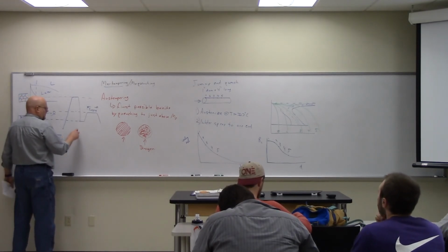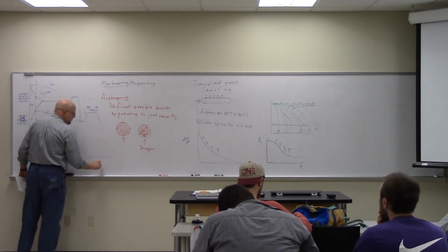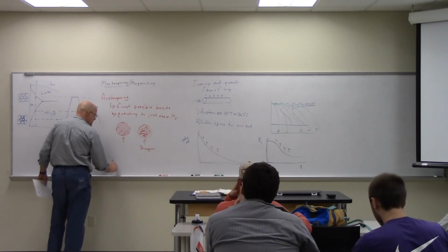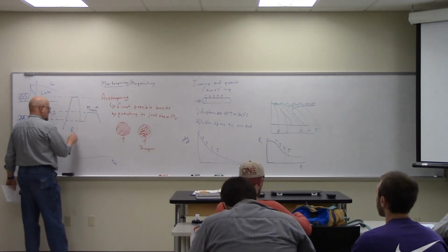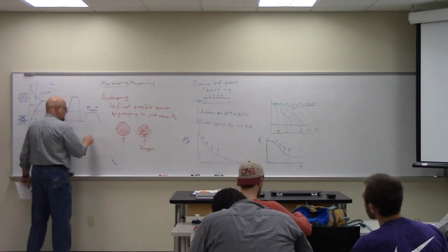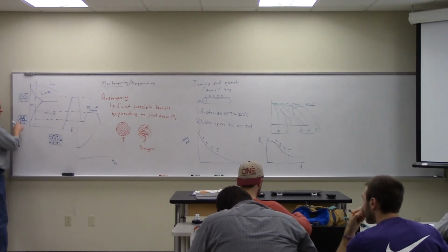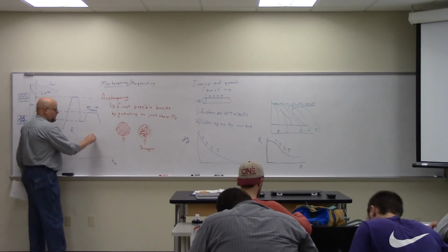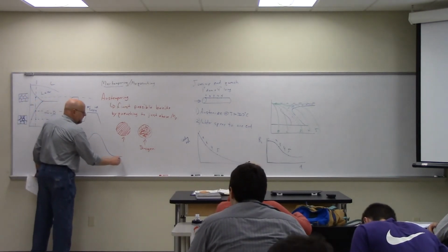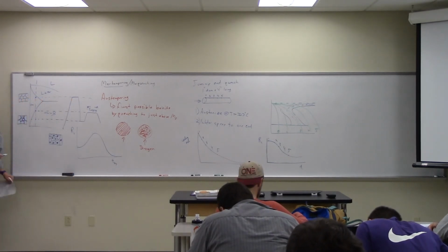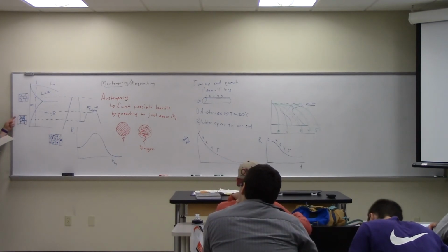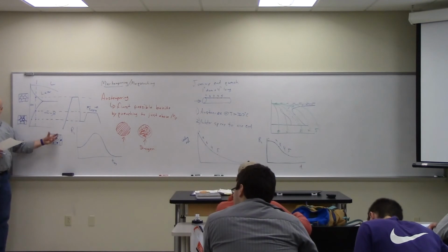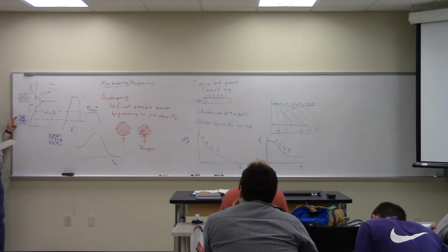And so, if I plot the hardness as a function of aging time, and again, hardness here. If I age it a little bit, I get an increase in hardness. Right, so I'm moving from this structure to the polka dotted structure, but then if I overage, it actually softens the material. Because now even the grain boundaries aren't good. Now I don't even have beta at the grain boundaries, so I have these beta chunks. And the beta chunks interfere with less of the dislocation motion than the beta grain boundaries.